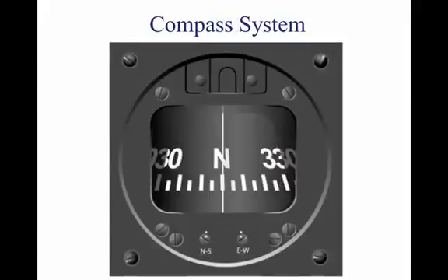One of the oldest and simplest instruments for indicating direction is the magnetic compass. It is also one of the basic instruments required for VFR and IFR flight. An aircraft magnetic compass, such as the one in Figure 7-30, has two small magnets attached to a metal float sealed inside a bowl of clear compass fluid similar to kerosene.